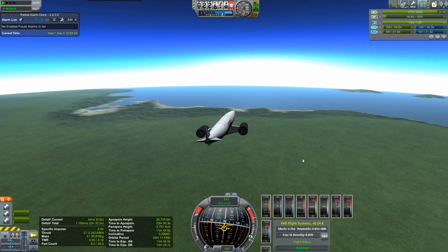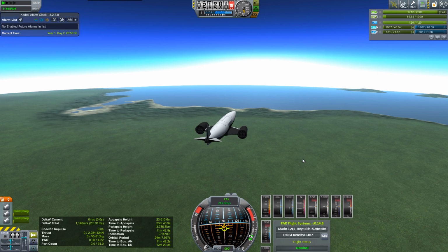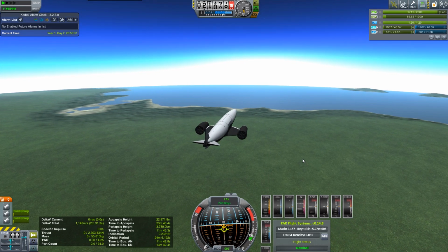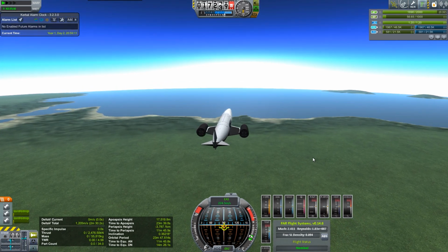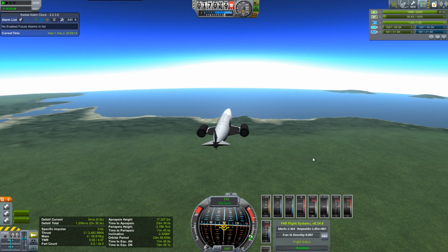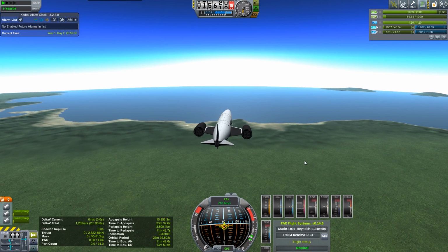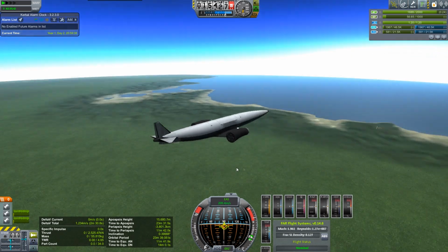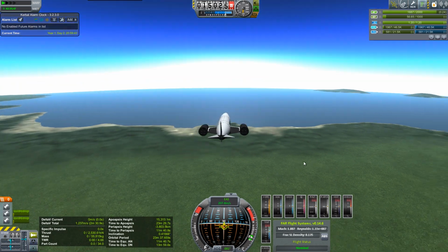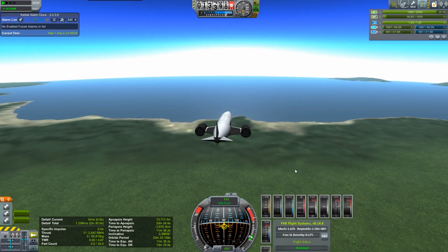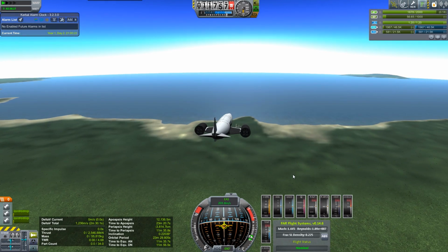Nice, more comfortable 1 G of deceleration. Equivalent airspeed is above 200. Let's start pitch trimming back a little bit more so as not to let that equivalent airspeed get away from us. Yeah, it's looking likely we're going to overshoot some. We'll turn around and come back. Or I suppose I could start doing some kind of S-turn type maneuver here, but really, I just don't want to get really excited doing these big dramatic maneuvers. We're still here at supersonic speed. Pitch trim forward a little bit more. Do faster descent. There's our equivalent airspeed increasing again.